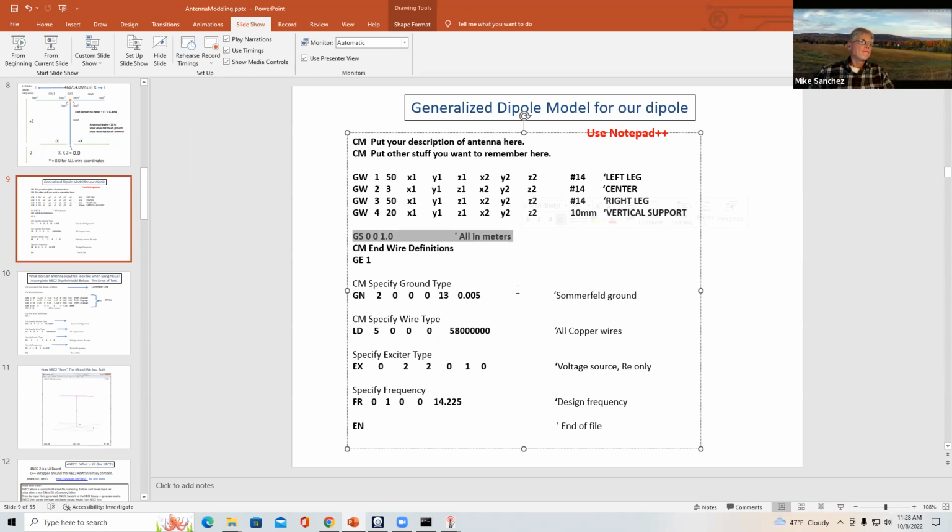But today I put it in so you guys know it exists, so that you can, if you want, program in feet, in which case you would put, instead of 1.0 here, since all of this antenna is in meters. So the scaling, this is called a scaling card. And since everything is in meters, the scaling will be 1.0. And during the model run, all of the antenna lengths will be multiplied by 1.0.